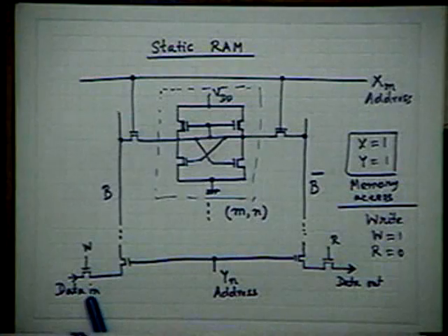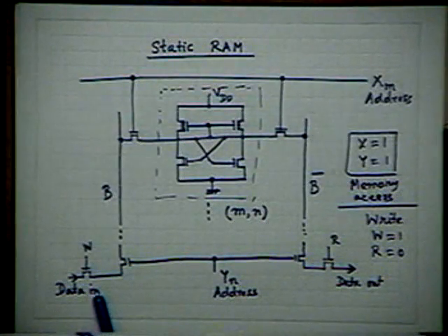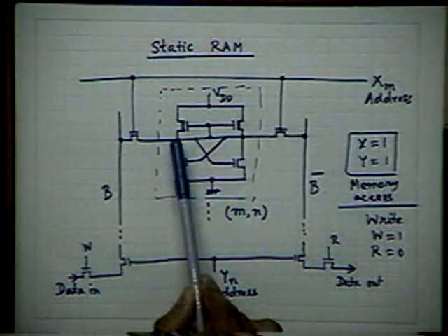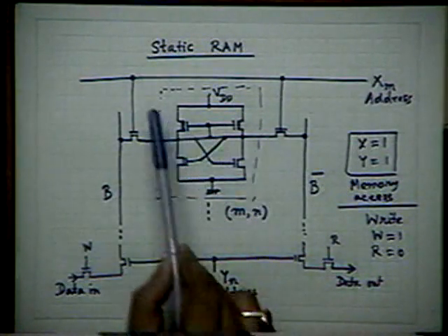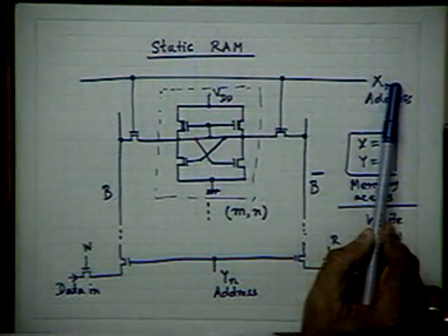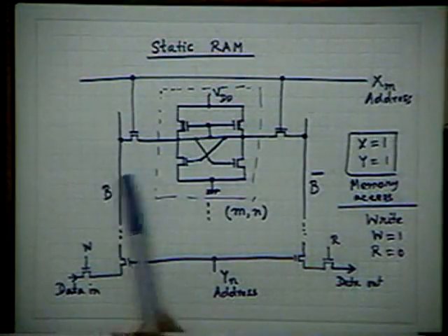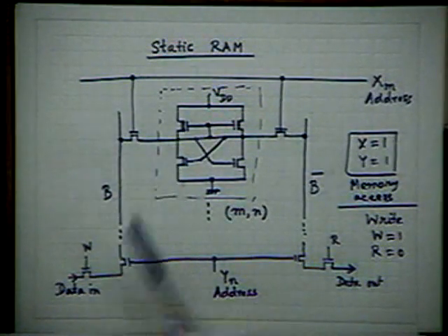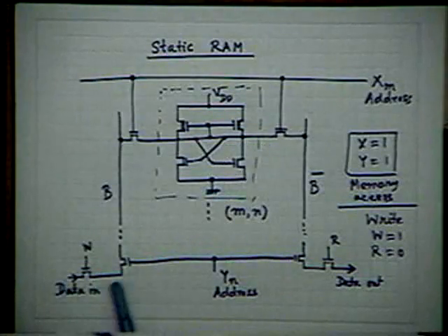Now suppose I apply data which is 1. And suppose it was 0, 1 initially, when you have made Xm equal to 1. Because this is 1, there will be a change from 0 to 1, and it happens cumulatively. Therefore, each element should have intrinsically very high gain. The corresponding inverter should have very high gain if you want high speed. That's an important thing. So very quickly, it was initially 0, 1, but it will become 1, 0, because you have addressed 1 in this line.